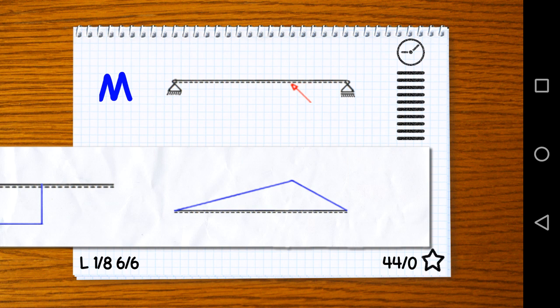But looking at this simple supported beam, at the right roller support the value of the moment should be 0. At the left pin support that value should be 0 too. And with this loading going upward when it comes to the vertical components, we should have a bending such that the tensile stresses will be on the upper side of the beam. So the moment distribution will also be on that upper side, meaning negative values, and due to the single load we need to have a kink, so the right answer here is correct.